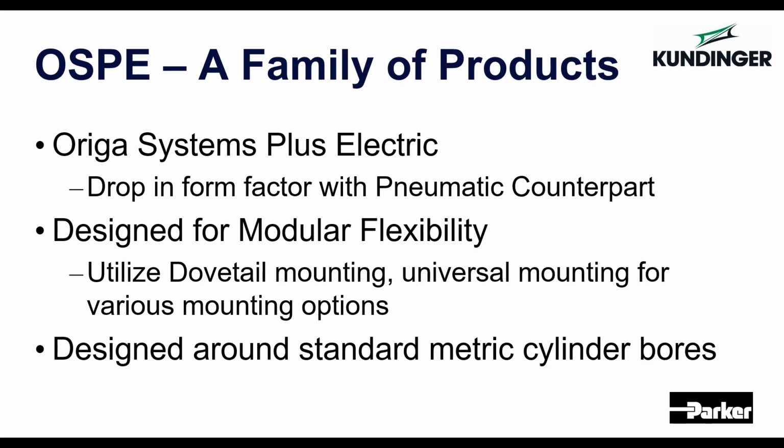So square rail bearings, these are by far the highest performance mechanical bearings that we offer. In a lot of cases, they're going to be deployed in dual rail setups, meaning very high loading, very high moment loading. Accuracy and performance is really based on the mounting surface. So in a precision type application, you may go ahead and grind the base that you're mounting the rail to for some very good flatness.